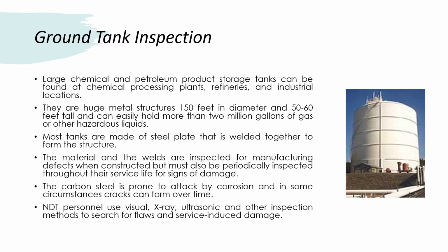Carbon steel is prone to attack by corrosion, and in some circumstances cracks can form over time. The NDT personnel use visual, X-ray, ultrasonic and other inspection methods to search for flaws and service induced damage.